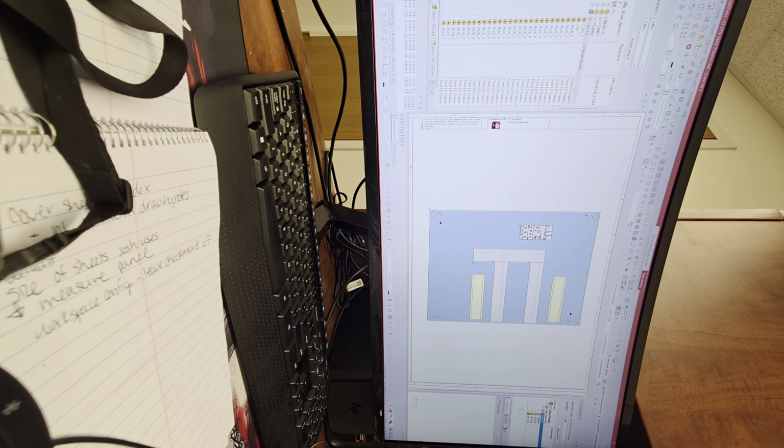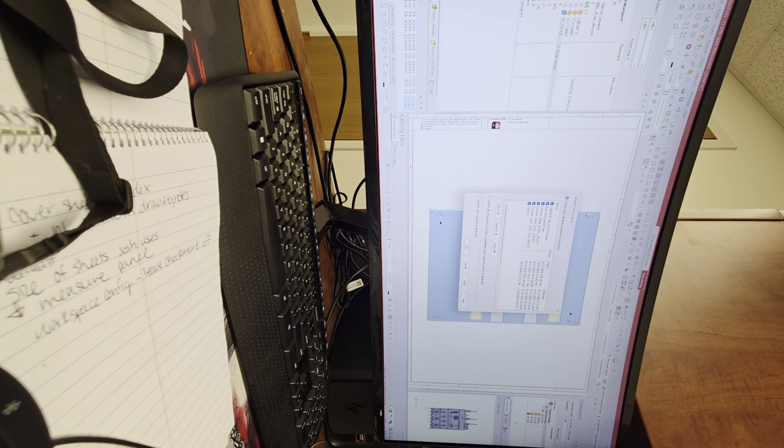usually, if you do this on the whole project level, instead of over the device, which would have been enough for what you just did, but if you do it on a folder level, like the solid state relay folder, one level up from where you currently selected, if you do update all components in project here, it's going to flag every single item that was ever edited between you starting this project and you messing with the library on some level.